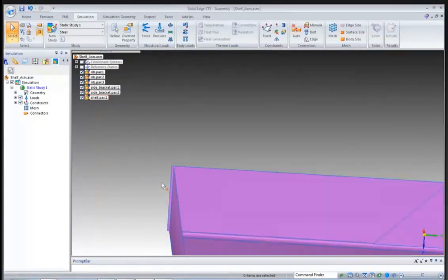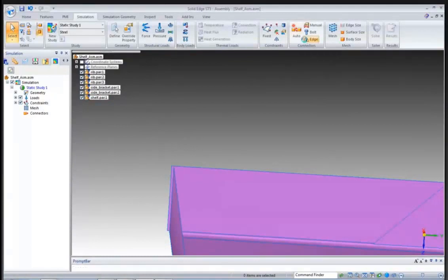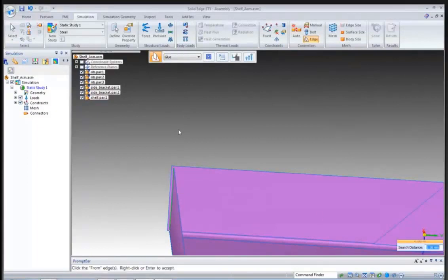So what if I had an edge connection? It's really more accurate if I had a true edge connection where the 2 edges were line to line. Then I would extend this surface out and trim it back till they touched, and I would use our unified body for that. But because this is really a T connection, I can use my edge connection and feel good about my results there. So all I have to do is pick the edge that I want.